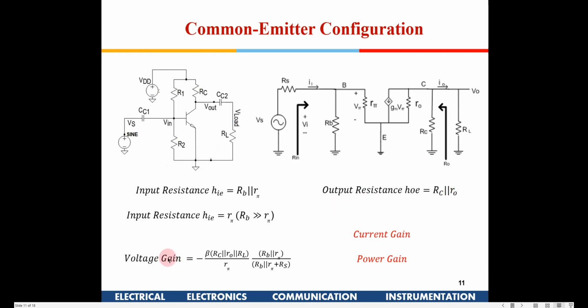Now if you see the voltage gain equation, if RL is very low, the entire voltage gain drops, right? So this amplifier works as long as RL is large. The moment RL becomes very low, then this amplifier is not suitable, because you will find RL is in the numerator of the voltage gain equation, and the moment RL comes to 5 ohms, 10 ohms and so on, you will find the signal is getting attenuated.